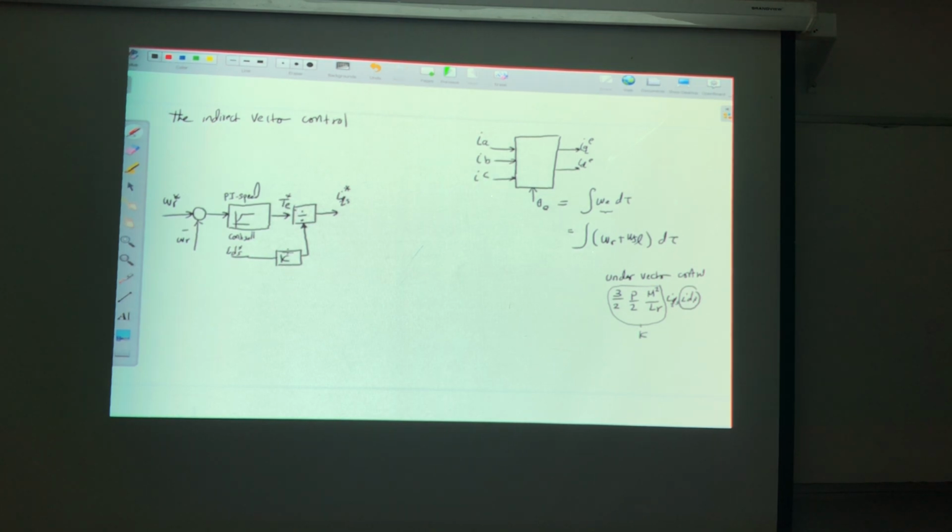So this means that T over this one, so I get here IQS, and also here I have the IDS. Now, if I have IQS and IDS, I need to do current control. For the current control, I can use hysteresis current control, the easiest one. So let's go with the hysteresis. For the hysteresis current control, I need an alternating signal.